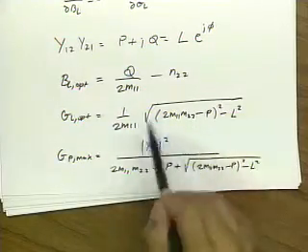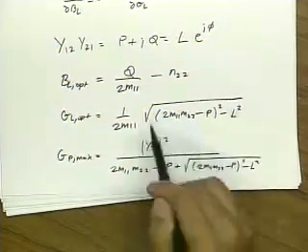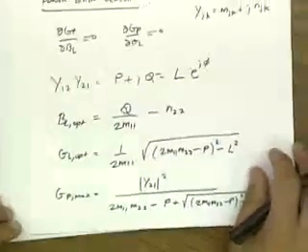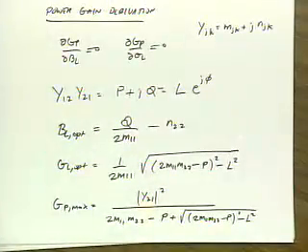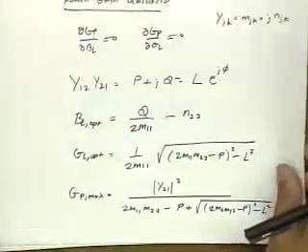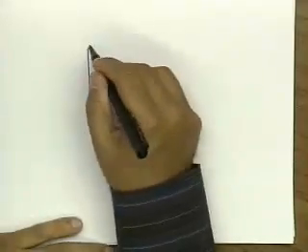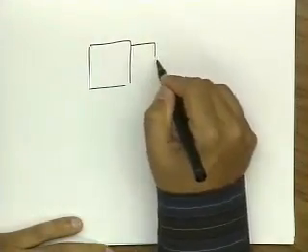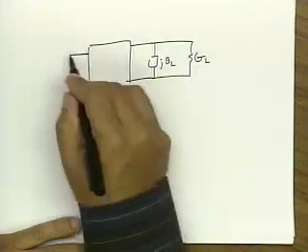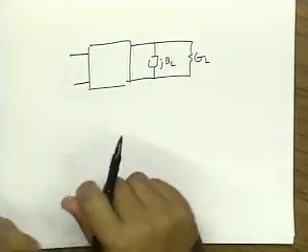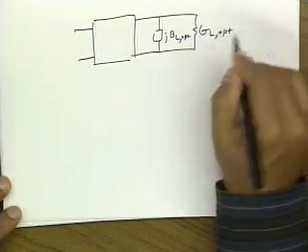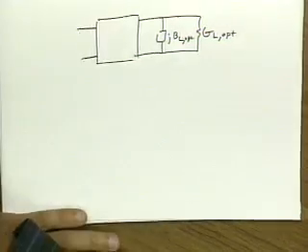Because this condition is so important, we're going to spend some time talking about the condition for an optimal solution. Before I do that, is the notation clear on this page? What's BL? This is my 2-port, and I'm going to terminate it in jBL and GL. So it's just notation, and what I found here is BL opt and GL opt. Thanks for asking that.